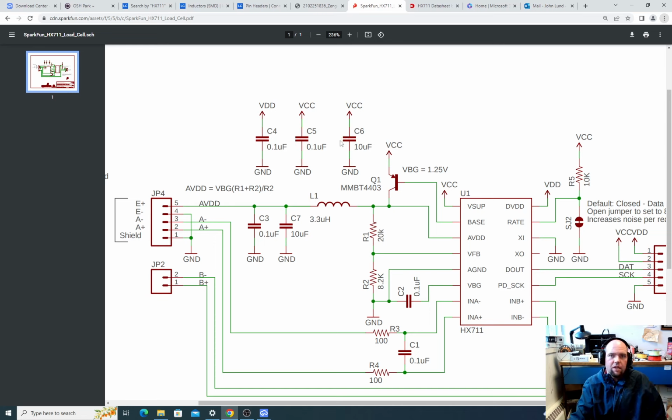These capacitors, decoupling capacitors, are just like having a water tower in a city, right? A water tower in a city stores water at a certain elevation, and it provides a nice constant water pressure to a city. Versus if you had all your water pumped from one source in a state, as you get peak water demand, as you start drawing water, you get water flow through that pipe down to the local city, and you're going to get pressure drop across that pipe as it flows. So instead, the solution is put water towers up in every single little town. That's what we're doing here with these capacitors. We're putting a little water tower up in every single town.